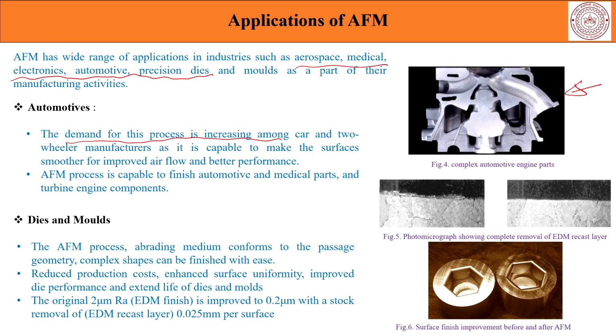But then again because of the recrystallization effect etcetera, and the melting recrystallization kind of layering which happens, it is important to planarize that layer, because it is random formation and therefore, the increase in roughness is obvious. So, therefore, all dies and molds typically have to go through such kind of finishing processes.